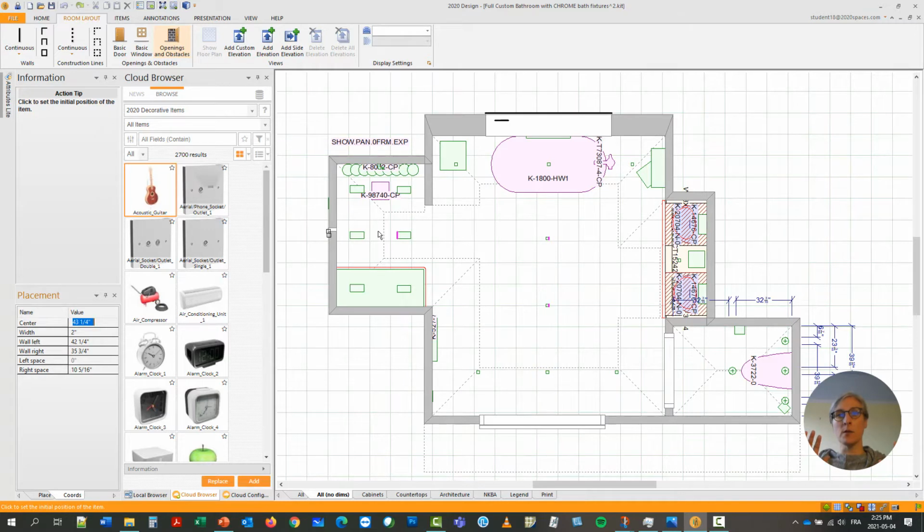I will leave the mouse alone and press Tab so we have the blue next to the width. Like this, I will be able to say how long my cutout will be. The one for this particular project is 55 inches. So I key punch 55 and I press Tab. Like this, I can see the whole overall size of my cutout before the final tuning. And because it's an object without any collision, that's why I can slide it outside of the wall.